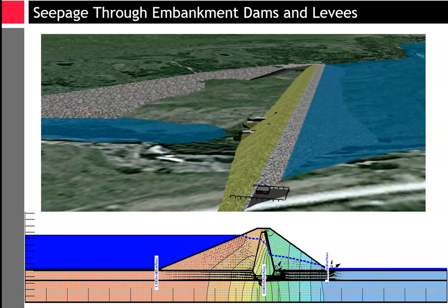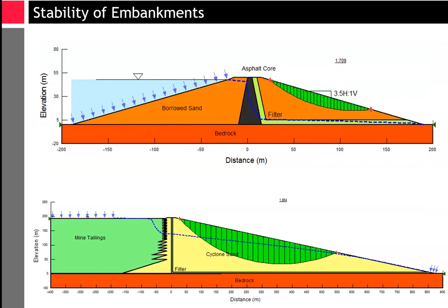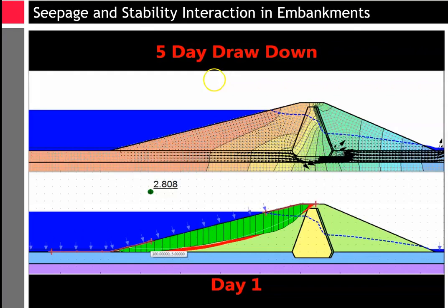So water flow through these embankments will be governed by the behavior of the soil, which we name the permeability coefficient or hydraulic conductivity. So by identifying those properties, we will be able to perform this seepage analysis, as you see, to see how much we can control and minimize the flow of water. Another application in embankment design will be checking the stability of the slopes that we have on either side of the embankment. And again, we will need those basic soil data, shear strength parameters, that we can use to get the slope stability analysis done.